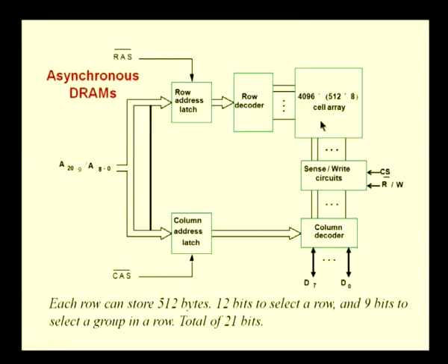That is because each cell consists of just a simple capacitor and a transistor associated with it. The space occupied by each cell is smaller, and you will actually be able to pack more cells in a given area. So, within the same cell area, a dynamic RAM is storing much more data than a static RAM, and it also makes dynamic RAMs cheaper than static RAMs.